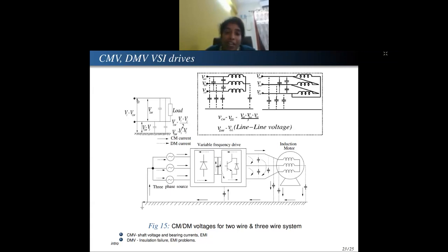So if you look back at the definition, between the wires the current can flow only because of the difference between V1 and V2, and from each wire to the ground, it can flow because of each voltage, V1 and V2. And if you collectively look at it, what gives the ground current is the average of these two. If you assume the capacitances are equal by symmetry, the VCM, common mode voltage, is V1 plus V2 divided by 2.